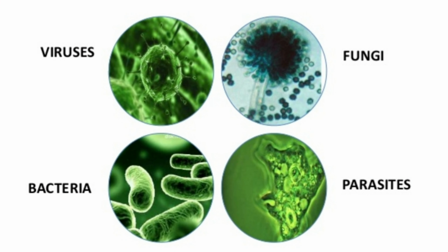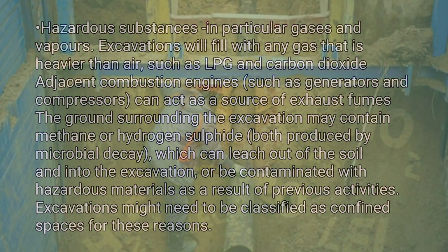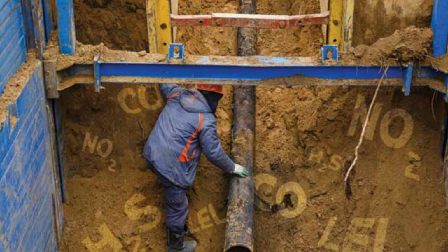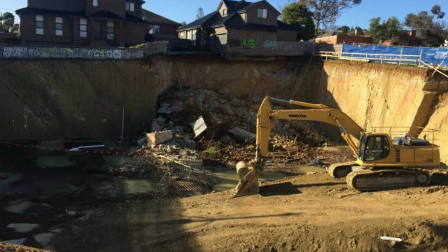The ground surrounding the excavation may contain methane or hydrogen sulfide, both produced by microbial decay, which can leach out of the soil and into the excavation, or be contaminated with hazardous materials as a result of previous activities. Excavations might need to be classified as confined spaces for these reasons. Collapse of adjacent structures. In digging and excavation, the foundations of nearby buildings may be disturbed, resulting in the destabilizing or collapse of the structure.